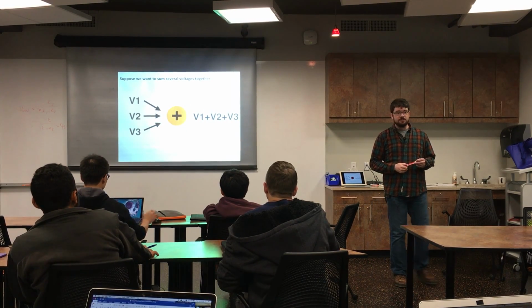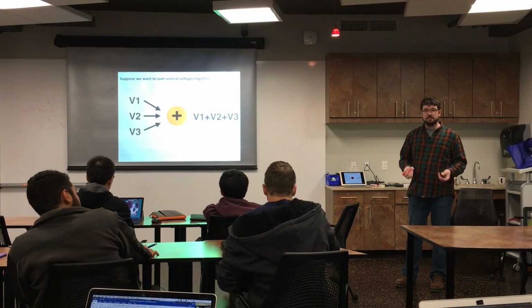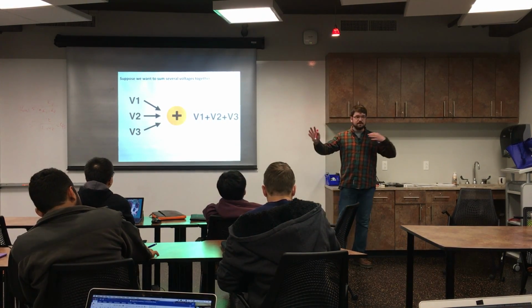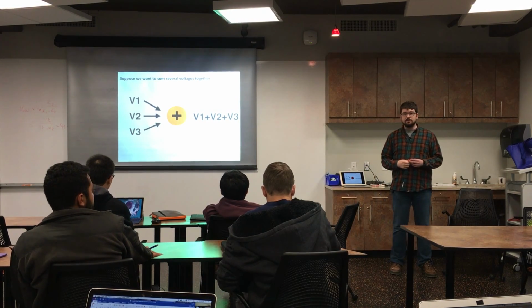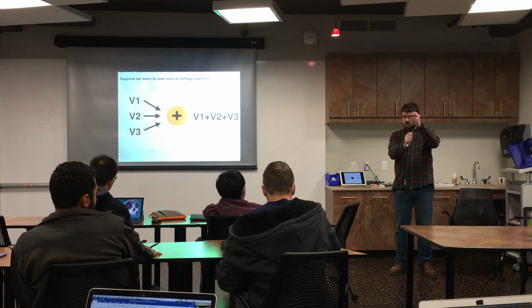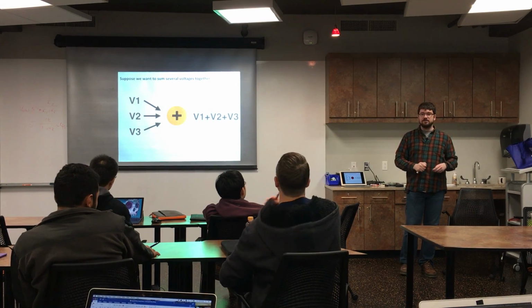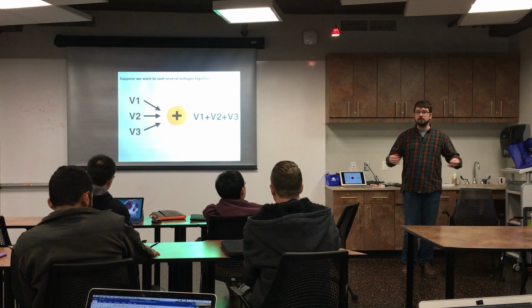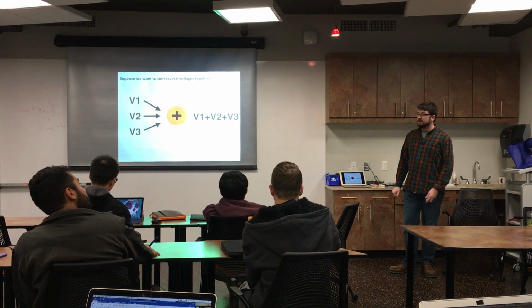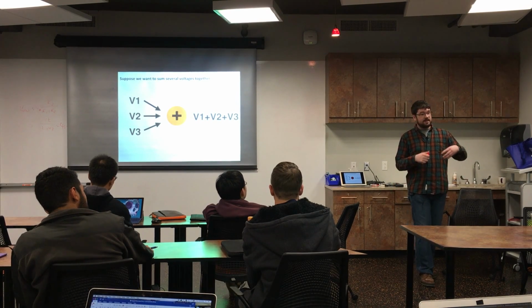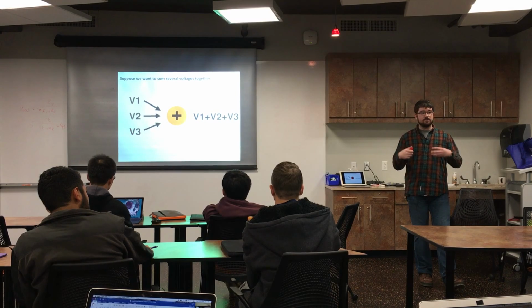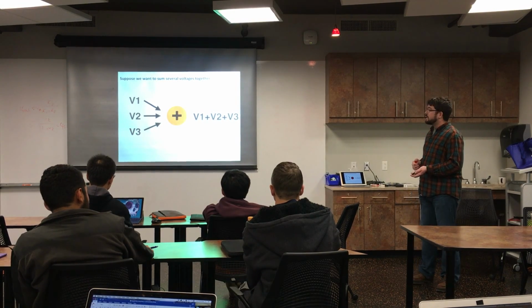Let's say that we have 3 voltages and we want to put them into some kind of a circuit, some kind of box, and on the output have all 3 added together, assuming that we've got enough voltage range to do that. You could come up with any kind of a number of scenarios for this. Say you had multiple transducers in a line and you wanted to add all of their outputs together to get total displacement on something or total force on something. Or you can imagine any number of situations where you want to add things together. Sure, now we have many channel digitizers where you could digitize everything and record it afterwards. That may not always be the case in your setup though.